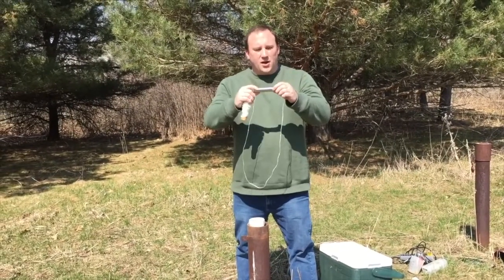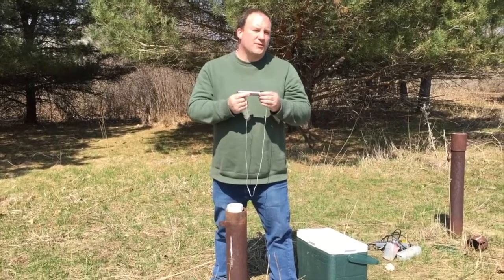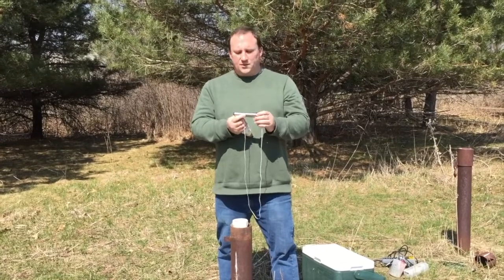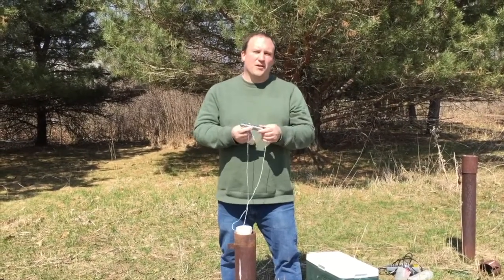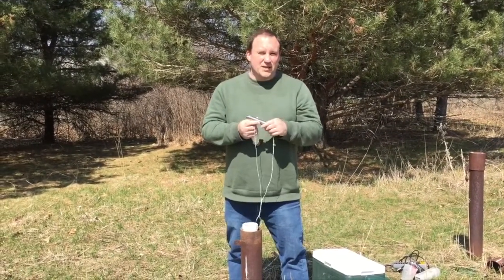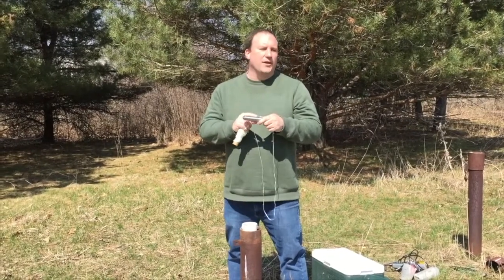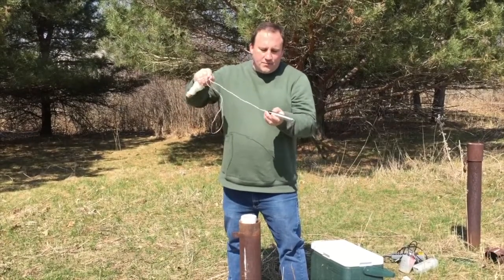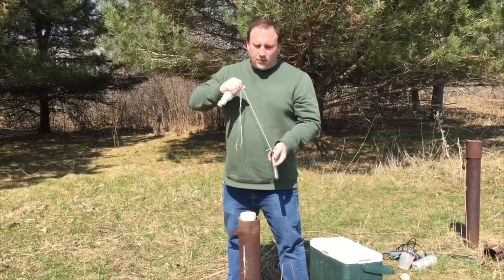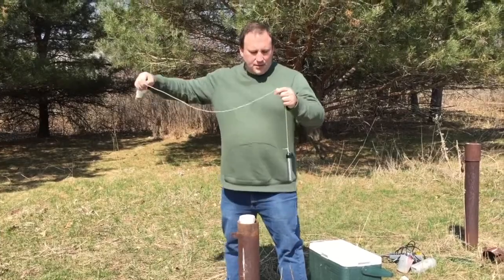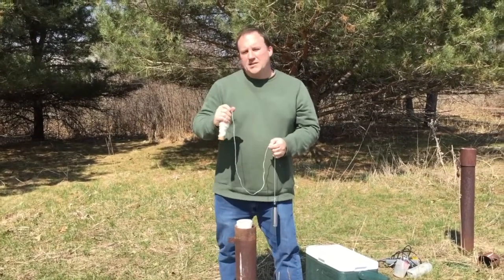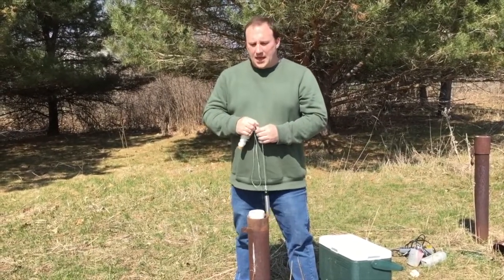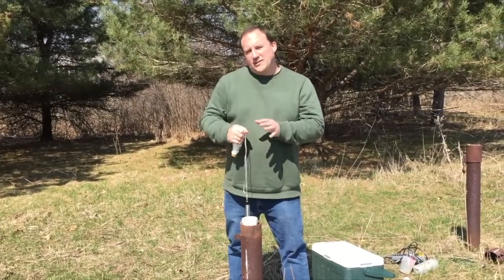Okay, so here's our data logger. All it is is a pressure transducer and temperature meter. There's a long-term lithium-ion battery in here, so this thing lasts for very, very long periods of time, like 5 or 6 years at least, before you send it back to the factory to have the battery replaced. And I've tied it onto a thin but sturdy nylon rope, and what I want to do is lower this down into the well at a place that's low enough that it will always be below the water table. And I don't know exactly where that is.